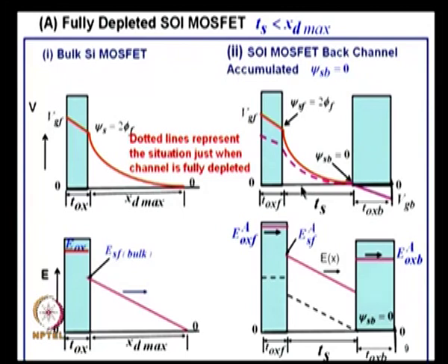I am applying it with respect to the substrate, that is, with respect to the source. So, the applied voltage, exactly in this case, exactly like this, will start appearing if it is not depleted fully. When the voltage is very low, some voltage appears across the oxide, some voltage across the silicon. Initially there will be a depletion layer starting from 0 here; the entire layer is not depleted initially. There is 0 potential here, and the depletion layer will start widening.